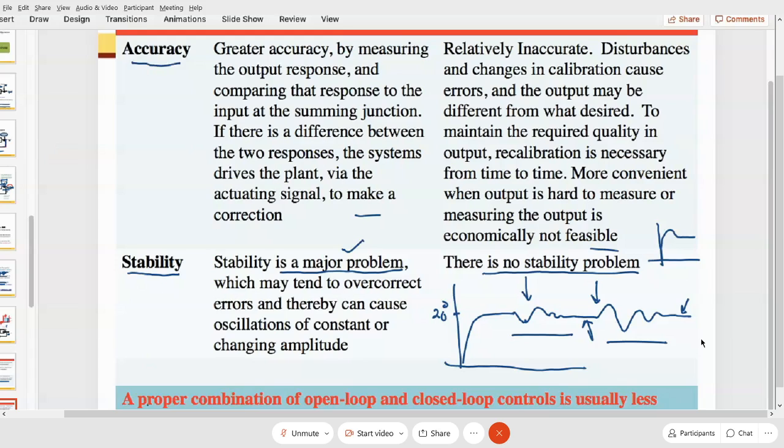It depends on the weight, and they decide what level of water the system needs. After they get the level, that is closed loop, and then you have the washing process. The washing process is actually an open loop system because they use a timer. A timer in a control system is open loop. So with a combination of closed loop and open loop, the system becomes cheaper.